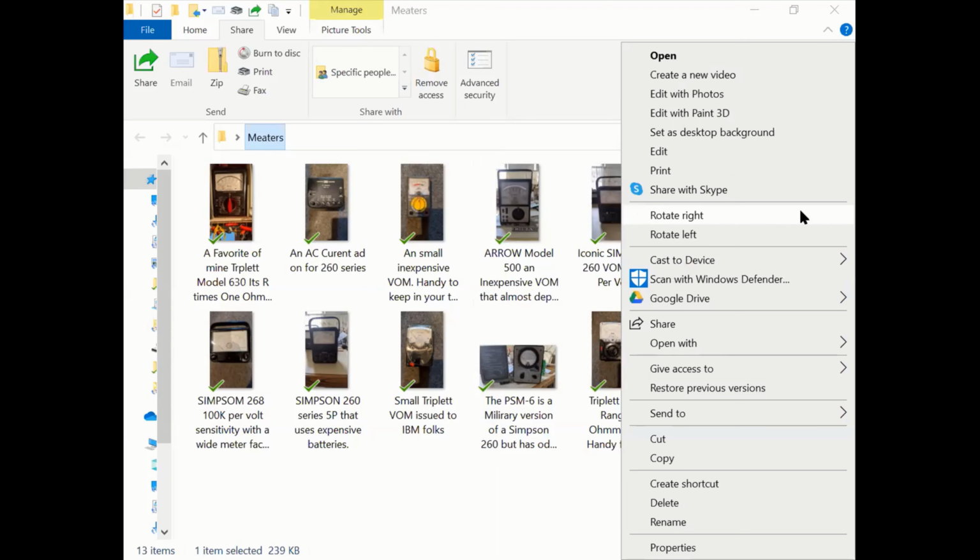is a PSM 37, which has a lot of fancy things. It's another meter that uses the same movement as a TS-352, but it's got decent jacks on it, and it can measure pulse current, whatever that is, but it's got 2 switches, and it's very similar. You'd have to consider it an updated version of a Simpson 260, military spec. It's waterproof and all that good stuff.